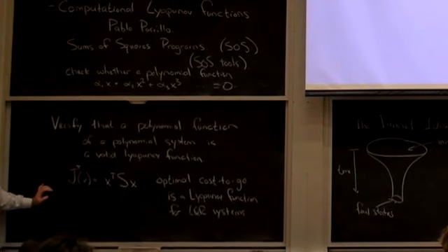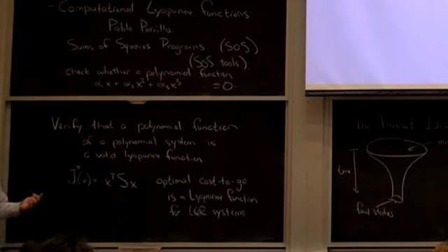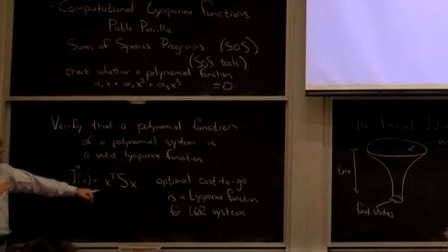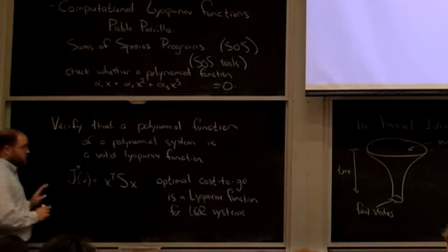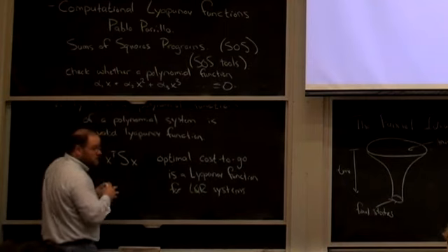If I have a nonlinear system where I've linearized it and done LQR control, then I expect this function to be a Lyapunov function over some domain where the linearization was good, and eventually to no longer have this nice negative definiteness property. Does that make sense? The optimal cost to go from LQR isn't a Lyapunov function for the entire state.